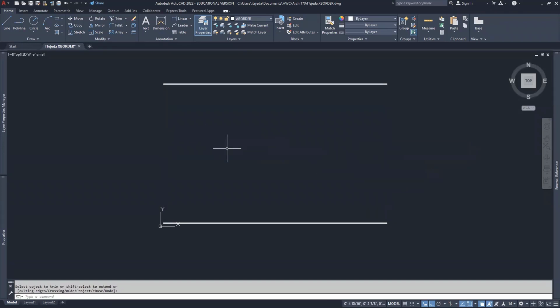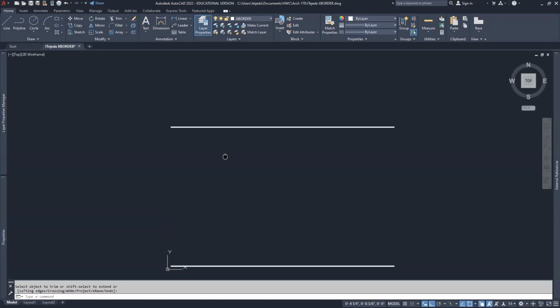here and enter. When you look at this, you might ask yourself, well, I could make it a line and then still give it a thickness, but no, you can't. This polyline here is unique. It only consists of one line segment. If I wanted to start with one single line segment from the very beginning, I could do that, and I'll show you a couple of ways.